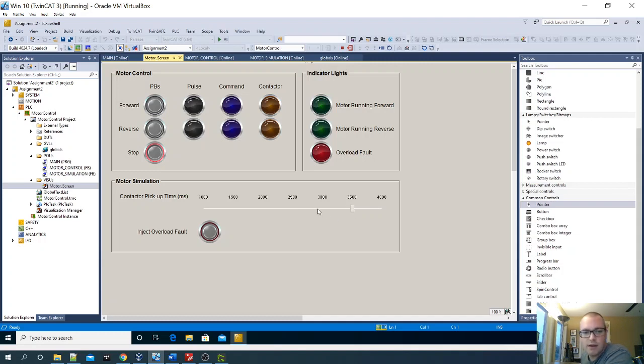All right. Let's suppose it's a bit faster. So within 1.2 seconds here. So I'm going to say go. And notice, boom, the contactor closes even quicker. The start pulse remains on for 3 seconds regardless, but the contactor closes fast enough that we can continue running the motor.